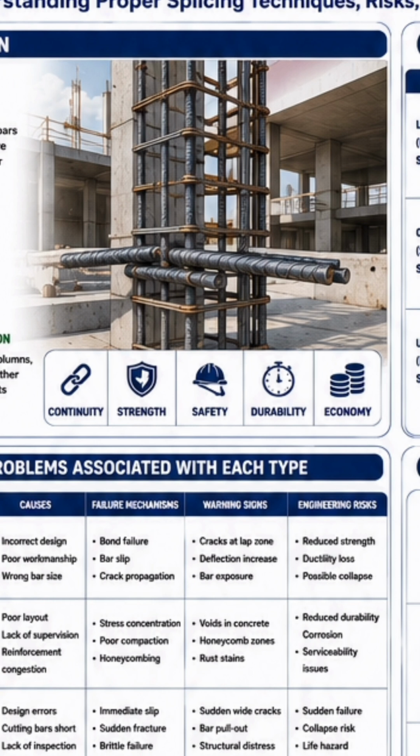It also helps you to economize, you understand, when you are constructing, instead of having maybe two different rods lying on the site as wastage. You can just merge them together, and considering the lap length, utilize such reinforcement.